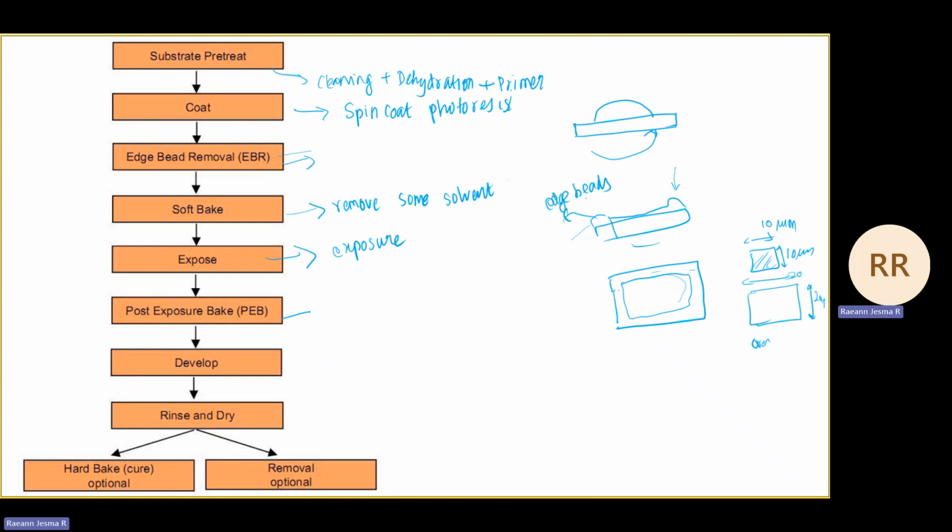So after exposure, we'll do a post-exposure bake for some time. Then we will follow this by development of the sample, and then we will rinse and dry.